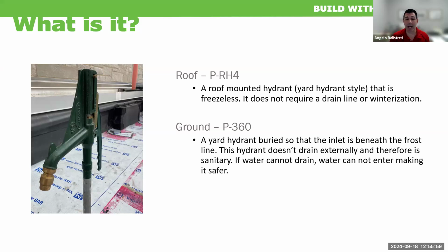And then the 360 side, we close up that weep hole. So on a drain or a frost-proof yard hydrant, when you close it down and you shut it off, there's typically a drain port at the bottom and a gravel pit that allows the water to vacate the system. So now you have a hollow product that can't freeze. That's the point of the frost-proof. Well, you have an open hole in the bottom of a hydrant. Well, what if you have a high water table? Water can get right into that same hole that is used for draining. So if you're utilizing this for certain applications, you may not want to be drinking or cooking or using that water because you don't know what's inside. So this